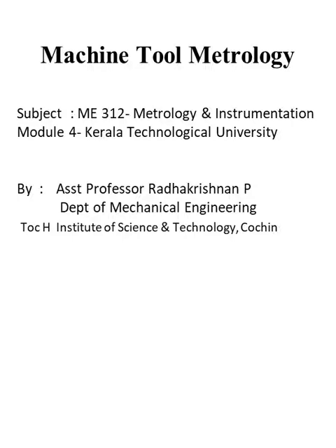There are many machine tools at present, and whenever a machine tool is manufactured, it should be tested for various purposes. Three different tests are mainly employed on machine tools: one is a static test, then a dynamic test, and a practical test. Static test means mainly it is an alignment test, that is, the alignment accuracy of various parts of the machine. That is called a static test.